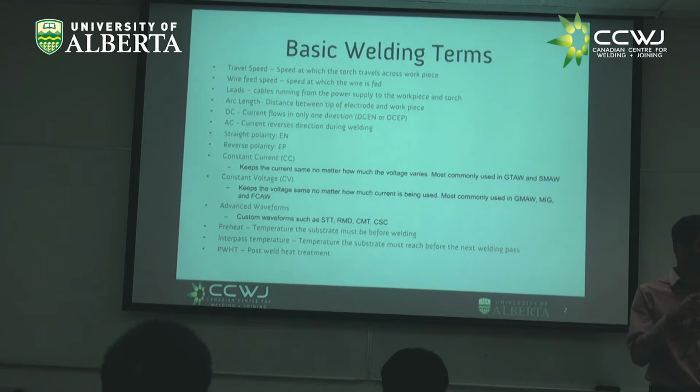Timaris? Corrosion caused by the chromium melted in the microstructure. It didn't melt, but what you said is right. You know the name for that? It's called sensitization, right? So if you have a stainless steel and it gets too hot, you have some little chromium, some little carbon there.